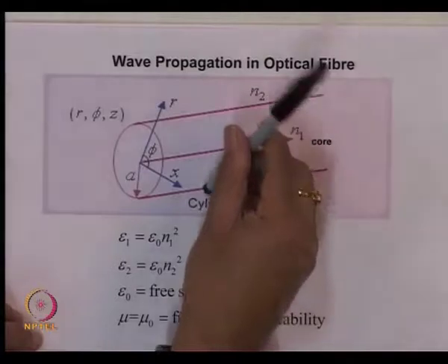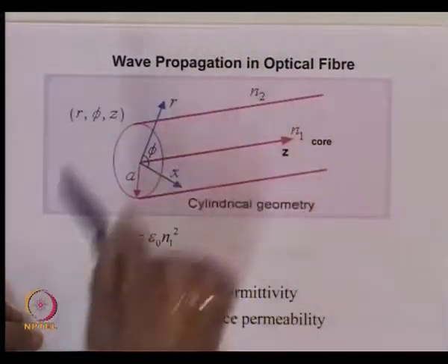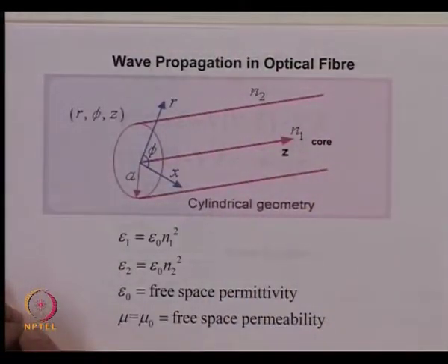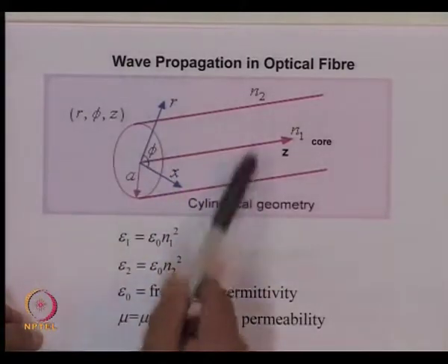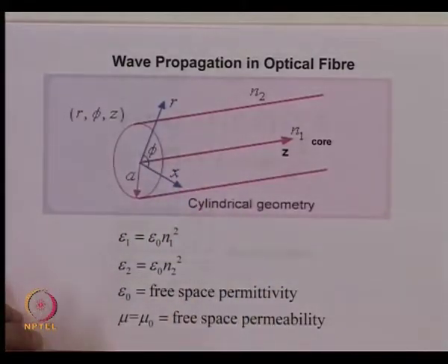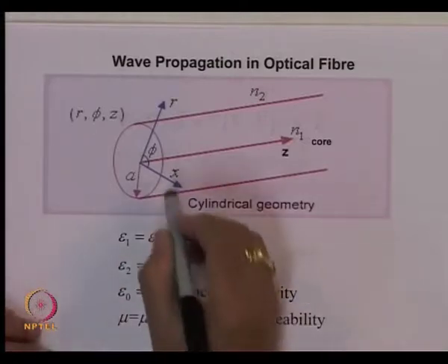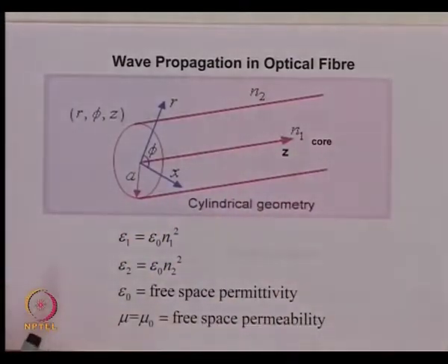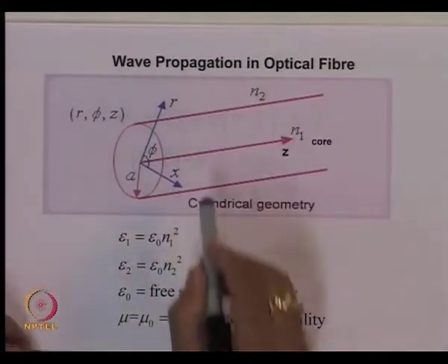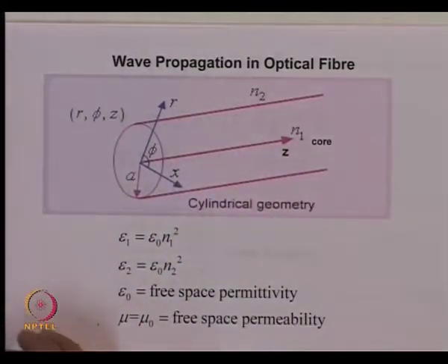Any direction which is perpendicular to this, which we call the transverse direction, there is nothing special about it in this cross-sectional plane, but this direction is a special direction. So, what normally we do, we take the two field components which are in the direction of propagation as the independent components and try to express the remaining four components in terms of these components.